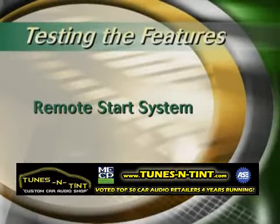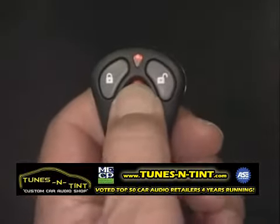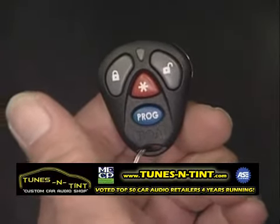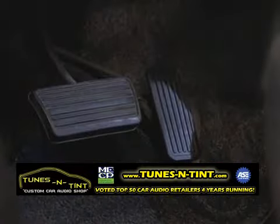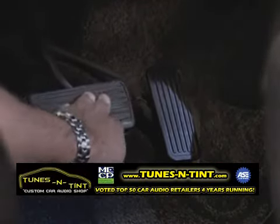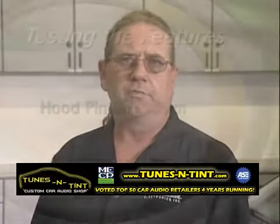Number two, remote start systems. For remote start, press the start button. Now let's test some of the safety shutdowns. Brake shutdown. With the vehicle in park, activate the remote start system. Once the engine is running, press the brake pedal. The engine should shut down immediately. If the engine continues to run, check the brake circuit connection.